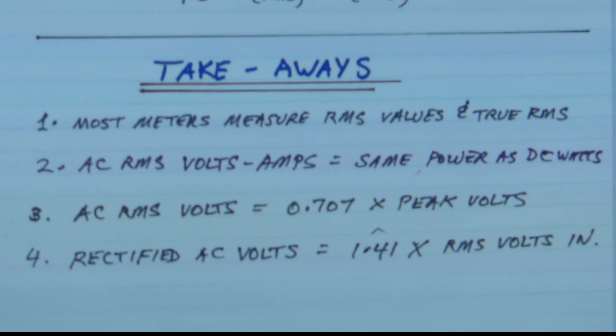But ordinarily when you take your meter and you're measuring, you're usually dealing with a sinusoidal waveform. You know, you're checking your power waveform, maybe 60 hertz in a circuit or whatever. So true RMS isn't really needed for those type of measurements. But sometimes it is, and sometimes then you have to have a specialized meter. You pay more for them, but it'll give you the true RMS value.